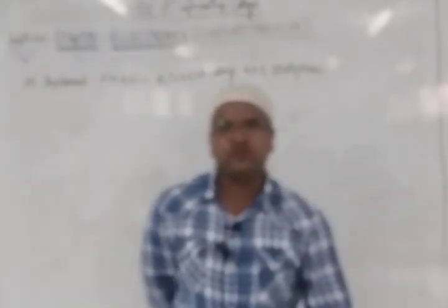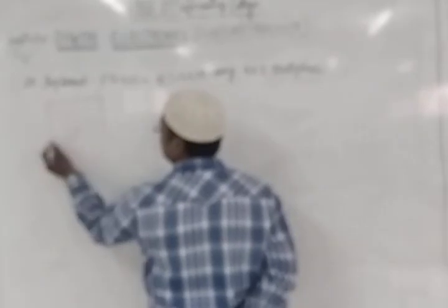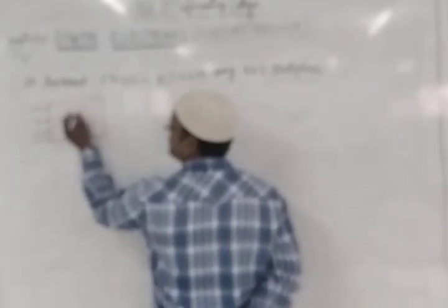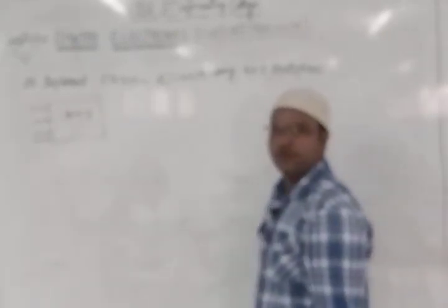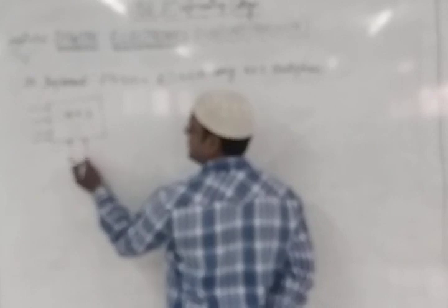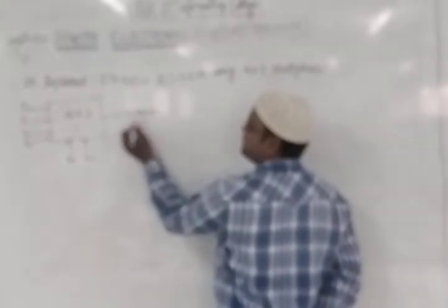So what is a 4:1 multiplexer? It should have 4 inputs. So this is 4:1, and 4 is nothing but 2 squared, which means it has 2 select inputs. I'm just mentioning them as S0, S1. It has inputs I0, I1, I2 and I3. It has one output, right? This is your output O1.